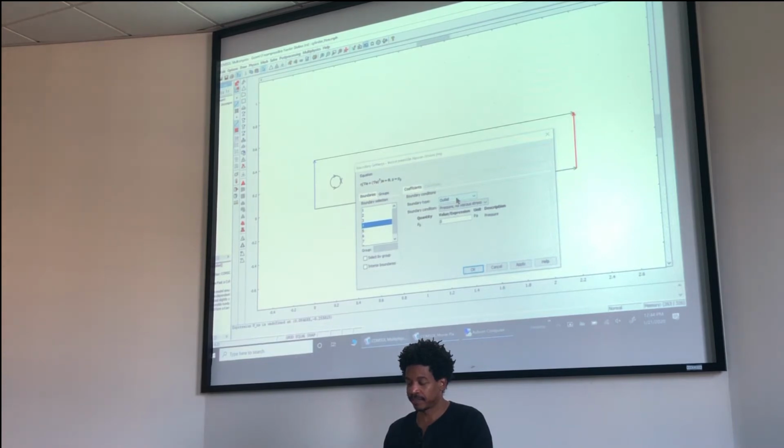So I can name it other things, but it's called an outlet. And the boundary condition: pressure, no viscous stress. All right? And the pressure is 0. All right, so now this boundary condition right here, this is just a wall, okay? And it's no slip.